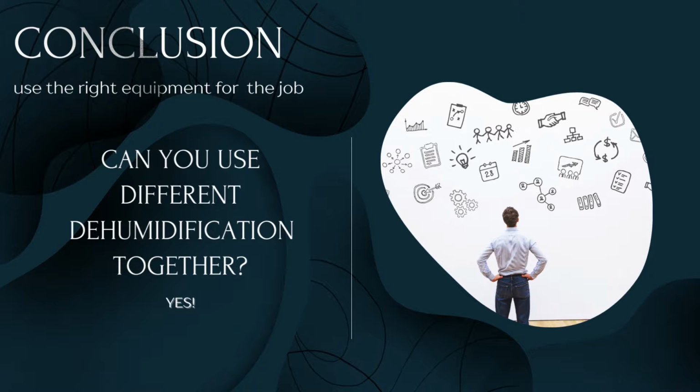If it's cold in the building, your building materials are not going to give off moisture very fast at all, if at all. The bound water is not going to want to come out if the wall surface is cold. It'd be sort of like drying your hair with a hair dryer with no heat on it. It's just going to take a lot longer to dry. So you may have to heat the building up to do that. You may need extra heat.